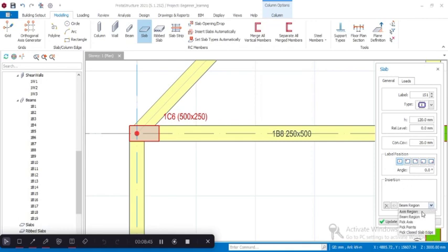You can insert through the axis region, if you want your insertion to be based on the axis region, the beam region, within the beam region, pick axis points, pick points, pick closed slab edge. So we're using the beam region because we've created our beams. In some situations where the beams are not there and I want to insert in the axis region, maybe a cantilever slab supported on one side, we use this. As we continue to work with Prota, you continue to see all those things.